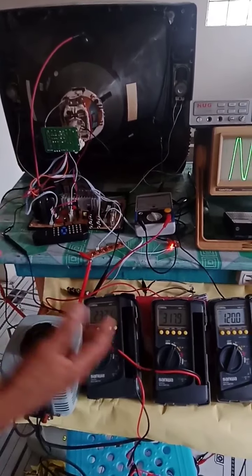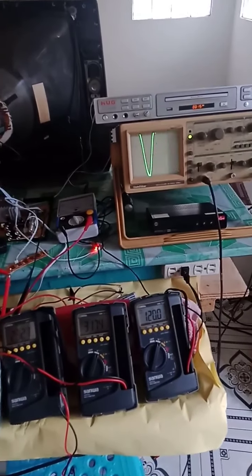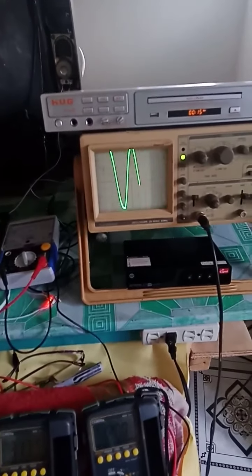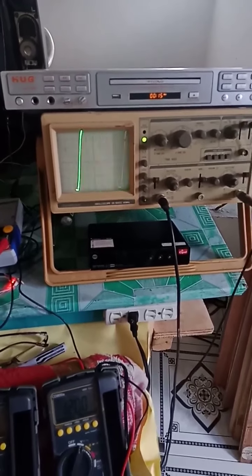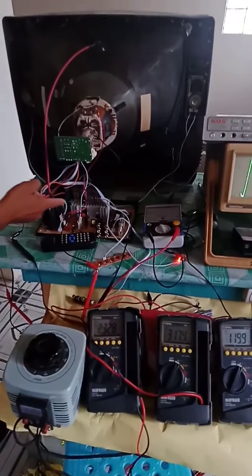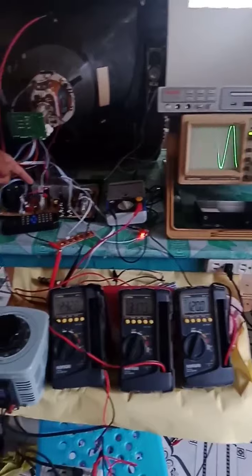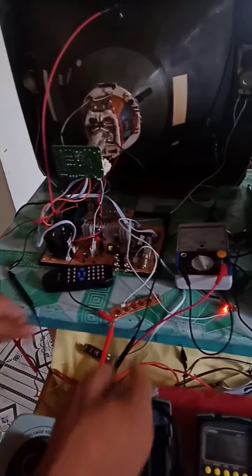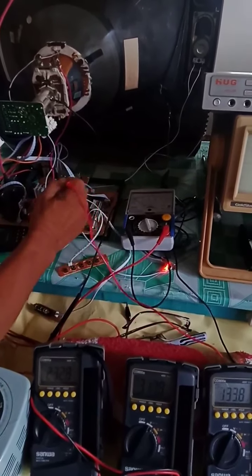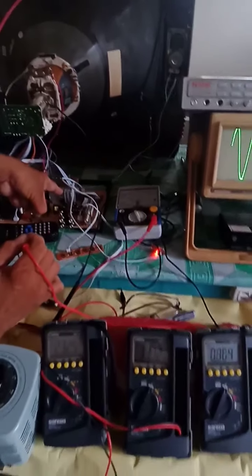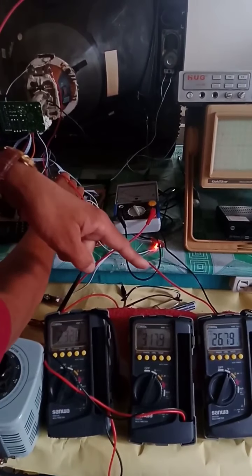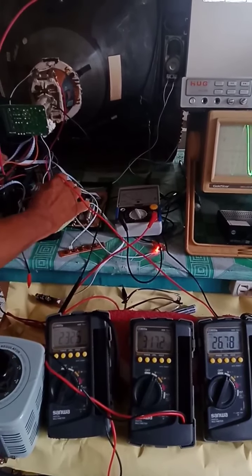Actually, the voltage at the outlet is prone to variation. It bumps up and down every now and then. That is the essence or the importance of the regulator under this low voltage power supply. So, the low voltage power supply is distributing 120 volts now towards the horizontal output transistor. It is not only 120 volts being provided to the circuits, but also there is voltage supplied to the vertical output IC. Look at this one. It is 26 volts provided by the low voltage power supply.